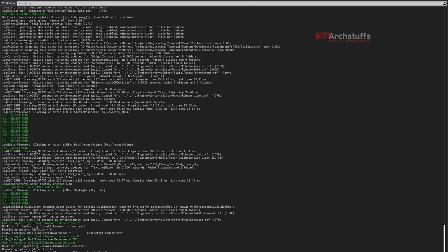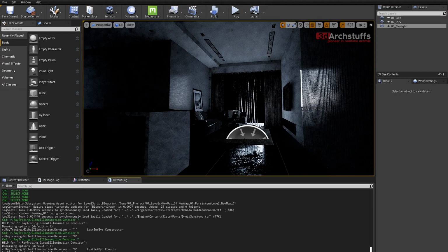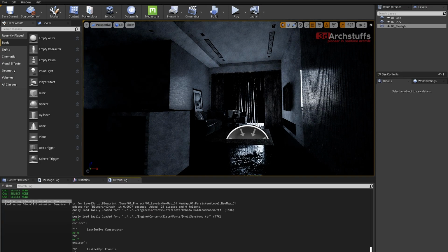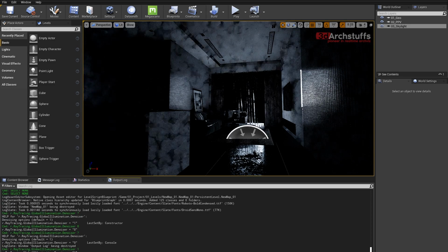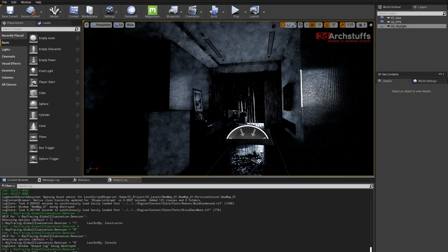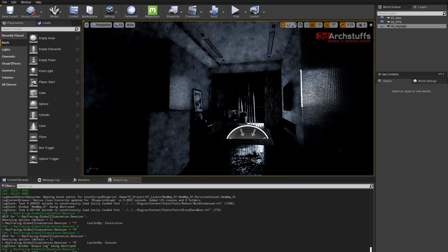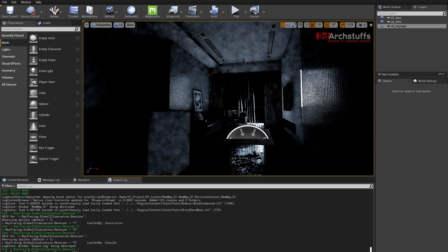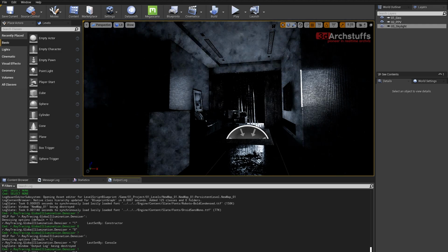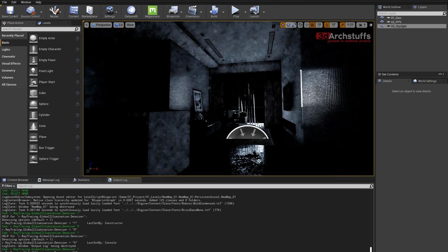So to make this permanent, so that every time I open the Unreal project to work on, the global denoiser is not activated and making things worse. Let me drag this here, and I will show the exact effect of how bugged this global denoiser is. If I go ahead and apply this, one will be switched on, so you see how bad it is now. It is supposed to denoise the GI, that means GI should be even better if it's on, but GI is very bad here. You can clearly see in the scene.